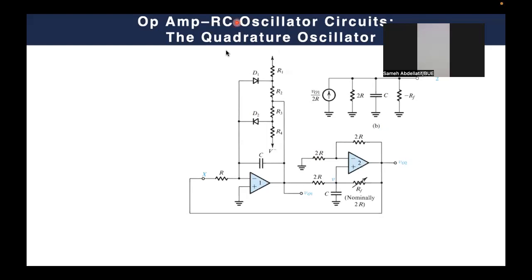Let's do the annotation and let's open here. So this is typically our amplifier. As you can see, our amplifier is directly straightforward. It's 1 plus 2R over 2R, or 1 plus 1, which is a 2. So it's a double gain amplifier. Very straightforward. But our beta network actually is not straightforward, as you can see, my dear students.